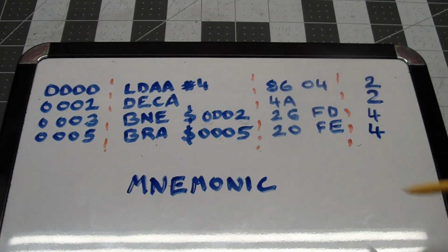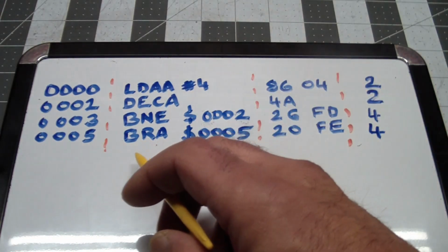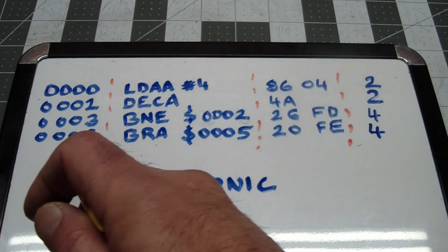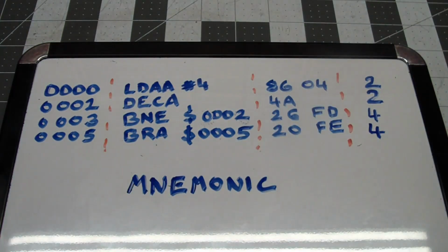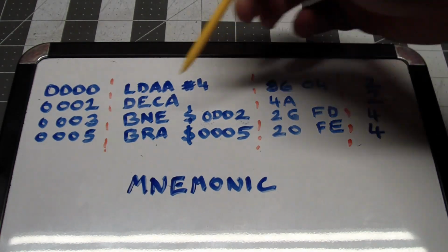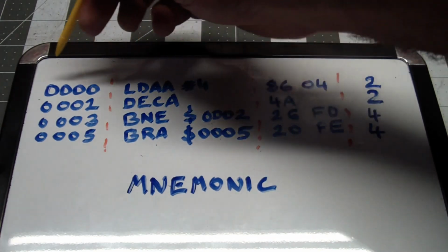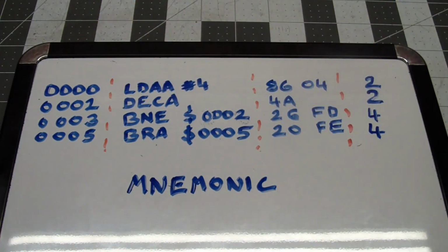It gets more complicated when you're actually coding these, because a branch isn't taken until the program counter is advanced by 2 and so on. But suffice it to say, the easiest way to remember is that you can go ±127 locations back or forward, and you need to use another instruction if you want to jump further.